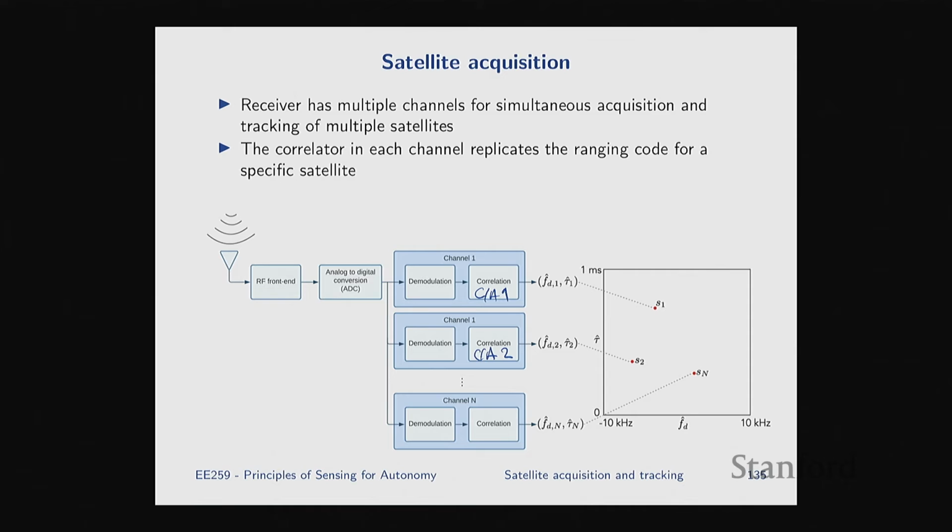Then if you feed the CA2 into this, you're not going to affect the output of the correlator because the cross correlation of these codes is very low. And that's part of the magic of these codes: this almost orthogonality through the correlation naturally filters out interference from other channels, right?